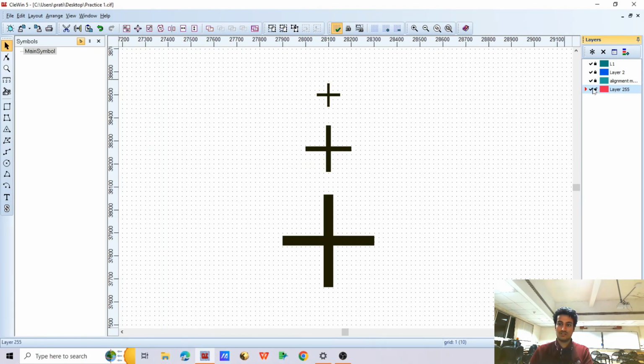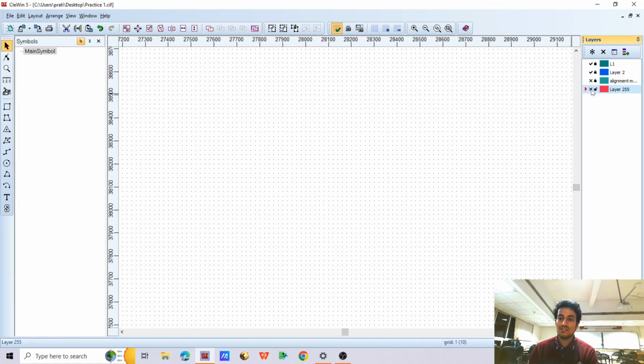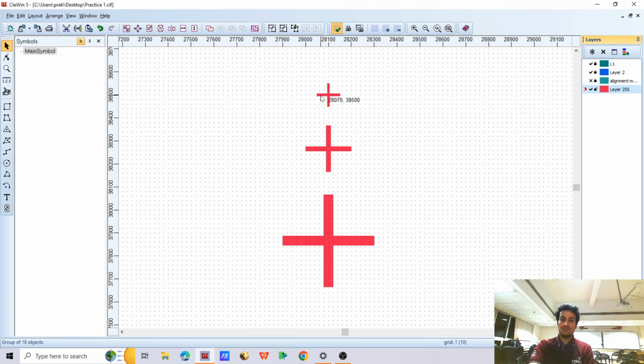So this first layer of the align marker will fit in the bright field of the same thing in the other layer, or I should say in simple words, how we will know whether this align marker is aligning with the second layer align marker? So we can reverse the polarity, or change the polarity, of this align marker in the second layer. So this plus or cross will fit in the reversed polarity of the same alignment marker.